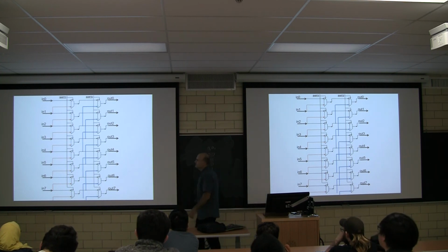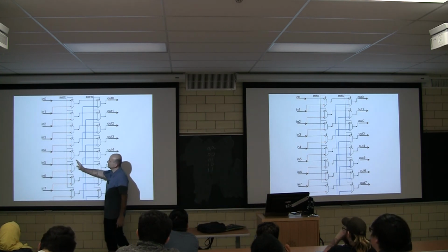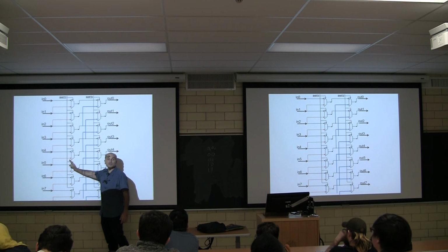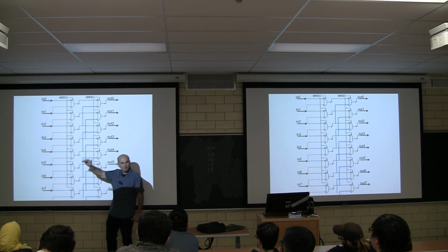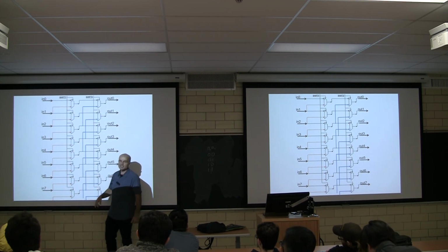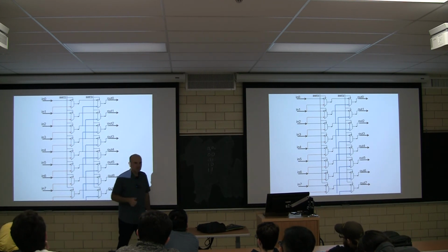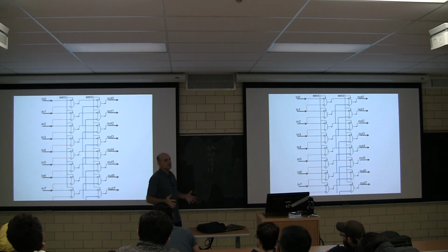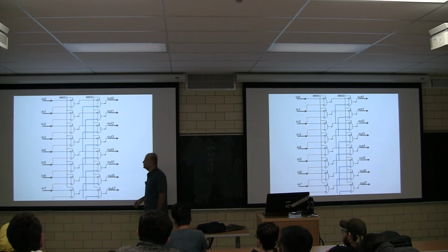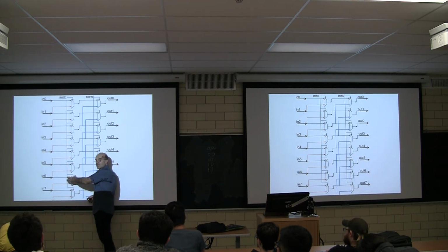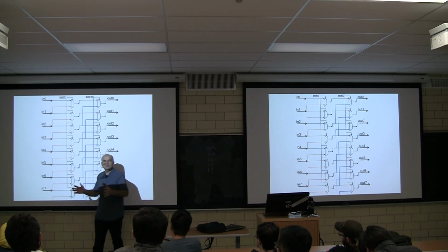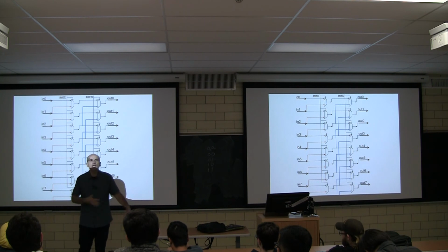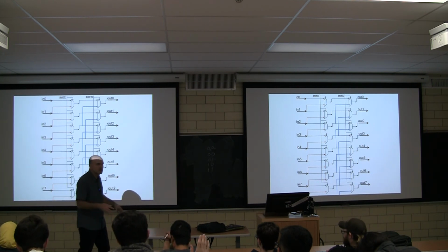Notice there is a first stage that is identical to the one before, which either shifts by 1 or not. The connections go from in 5 to the guy upstairs immediately, 1 floor up. In the second stage, however, the connections are 2 floors up. You can choose to first shift by 1 if you wish or not, and then whatever comes out, shift it by 2 or not. This circuit can do anything between 0 and 3. Fair enough? And you can keep going. It looks like a tree.